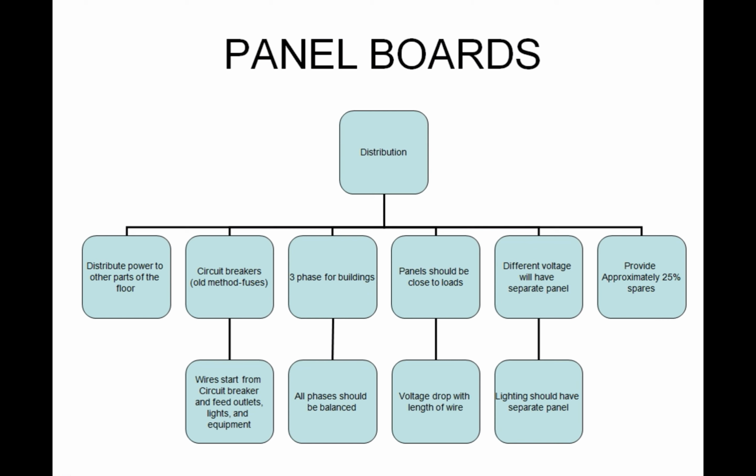So we want to have these things as close as we can to where we're using them. If you have different voltage sources, you have to have different panels so they can be labeled properly, and you don't hook the wrong type of equipment to it.